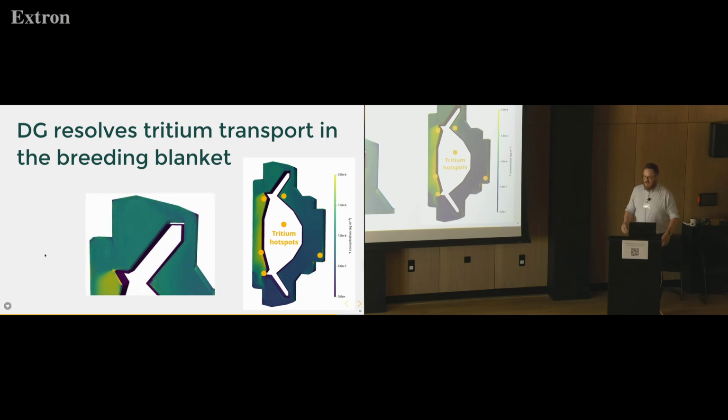And in this case, it's from doing all this multi-physics work that helps us refine the design of these different components. Because for instance here, what we're seeing on the top two segments is a lot of recirculation, which is in turn causing a lot of turbulence, which helps spread the tritium out so you don't get as much of a hotspot, compared to this zone here where we just get a lot of stagnation in the flow. And because it's not moving very much, the tritium just gets stuck there and isn't diffusing out. So it's in these types of workflows that we'd be able to help design these components to make sure that we can extract as much of the tritium that's being generated in this component as possible and as quickly as possible.